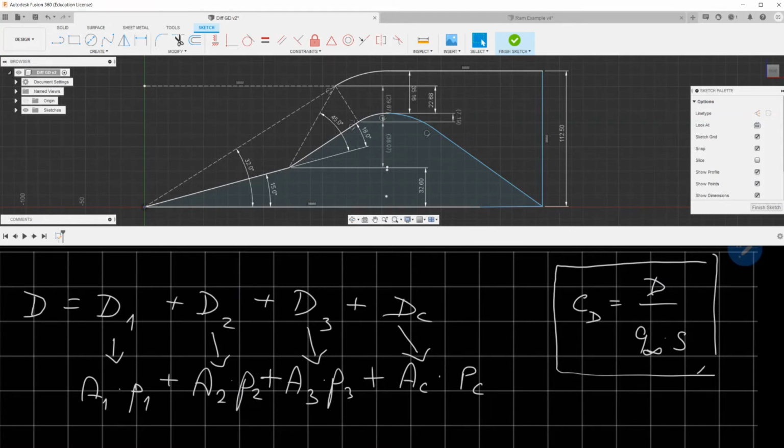I calculated the same way, the drag on areas 1 and 2, following the book's example, but I didn't really calculate on section 3 because in the arc, the component of the pressure wouldn't really be normal. So we are actually approximating the arc by a triangle in this case, by multiplying by the example, or because I was thinking I would have to use some kind of integral or something like that to calculate it, because the component normal to the pressure would be normal to the surface. Okay, so we have this P3A3 problem, right?